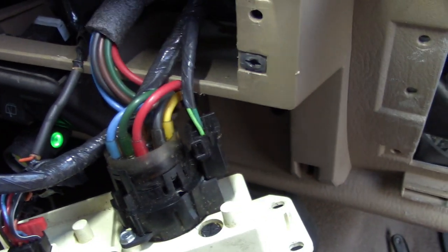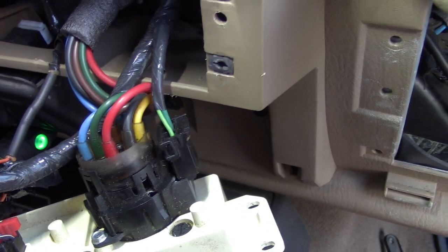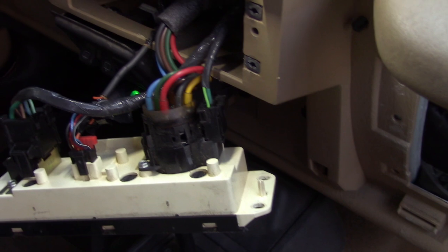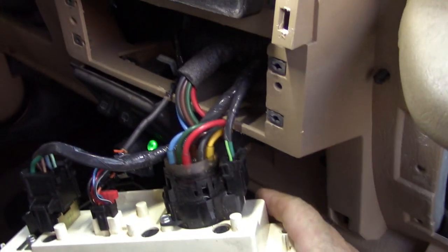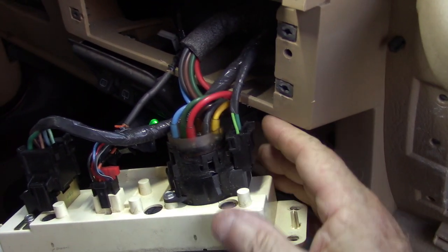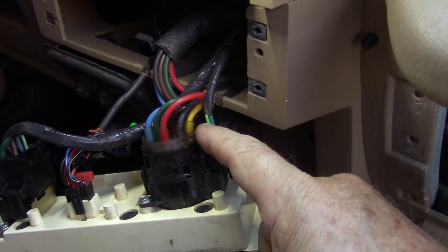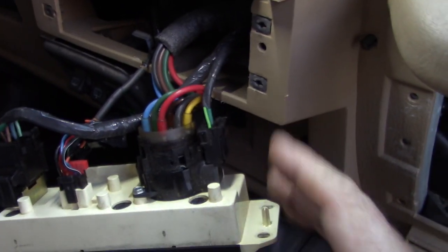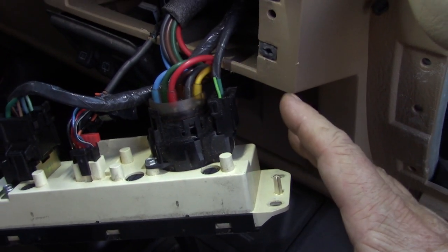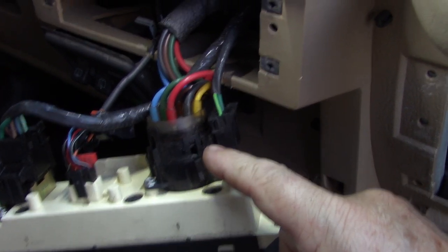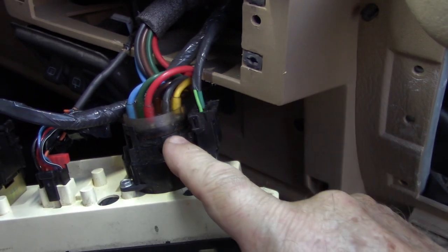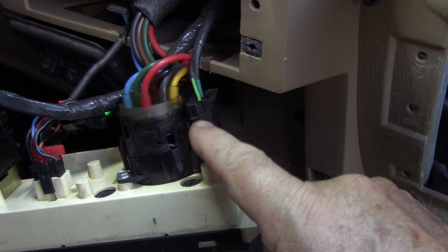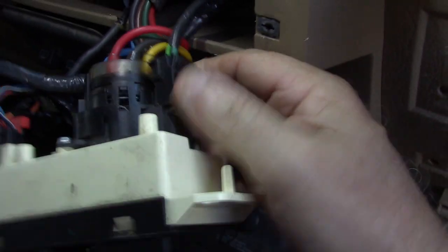So let me pause you for a second, and I'll be right back. Okay, I had to go take care of my test light so I didn't spark up anything. Okay, so we have power all the way to here, and we have a good ground. And spoiler alert, I had actually already diagnosed this thing, and I knew it was the switch. It's either the switch or this plug in here, because I was trying to unplug it.